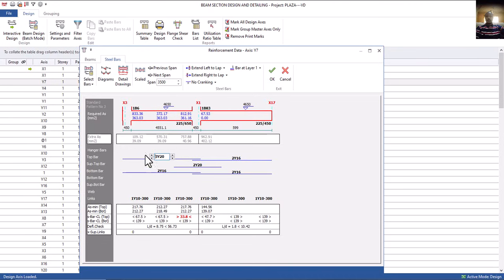Is that okay? But in this case, it's support and support, no problem. It's support and support, not a cantilever, and it's only this one that is a cantilever. Is that okay? So since it's only this one that is a cantilever, we can still go where we have 3y16 here, and then connected with 2y16. If you take care of this, because if you look at the span, it's just 500 and that just is 600. Is that okay? All right, which is okay.